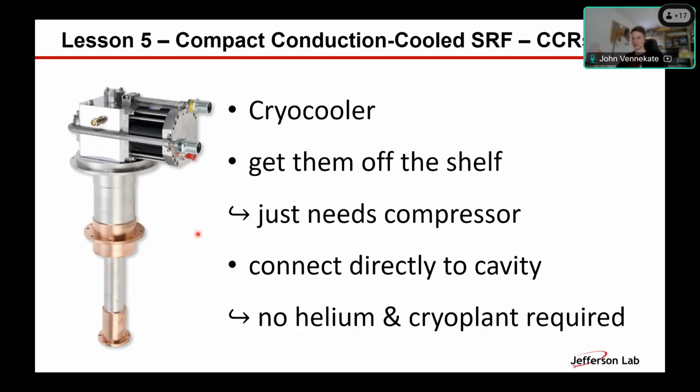And that's really, again, like I said, the second biggest pillar that our idea and invention is based on. That using these cryocoolers, you have an easy system to generate your cryogenic temperatures and to provide superconductivity on a small scale, at least. They obviously don't have the cooling capacity of a large-scale cryoplant, but they have a small localized option to provide cryogenic temperatures for utilizing superconducting technology for particle acceleration.